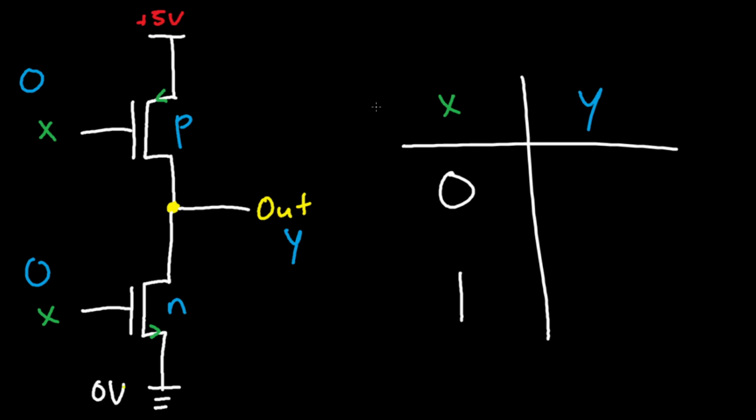And how about this for an n-type? Okay, let's write down closed here, actually. Well, for an n-type, it's the opposite, right? So 0 for an n-type stands for an open switch. The opposite of the p-type. So we have an open switch here. No current can go through this guy. So we have this 5 volts up here. Let's look at the path of this. Well, since this acts as a closed switch, oh yes, current can go through, and it hits this node. Therefore, this node has voltage as well. All right, this 5 volts can go all the way through and hit this node.